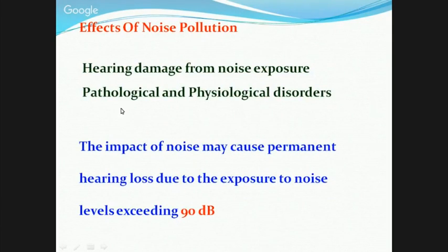And we have to see that noise causes damage to our hearing system. It also causes some physiological and psychological disorders in human beings. Any noise which has a value of 90 dBA, and a human is exposed to it for about 8 hours per day, will definitely go deaf after some time. So basically we have to see how much is being generated. We have the standards for particular areas, so we have to follow those standards in order to avoid the effect of noise pollution on us also.